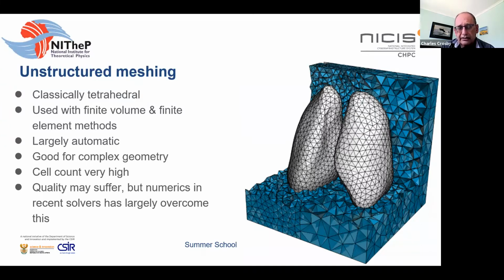A triangle is a nice thing to work with because 3 points always lie on a plane, and it's easy to hook them up in such a way that they share edges, so it's always waterproof. Well, the same thing applies to the meshing. If you take 4 triangles, they form a tetrahedron. And it's a relatively simple and easy method of filling a complete flow domain with a detailed mesh.